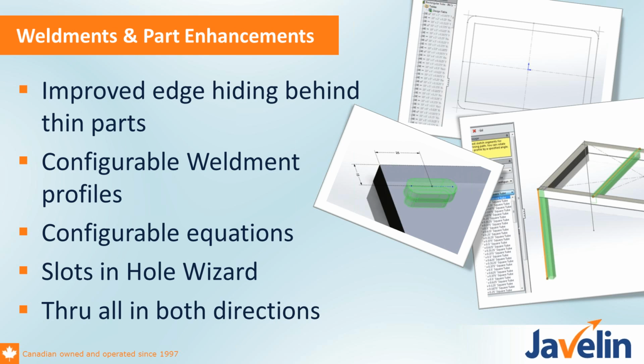Talked about configurable equations, which is nice too. This is a good example of something that's relevant for all part design. It's not just in weldments, but you can now have an equation which is only applied to a certain configuration. In the past, if you applied an equation, it was globally applied to all configurations.